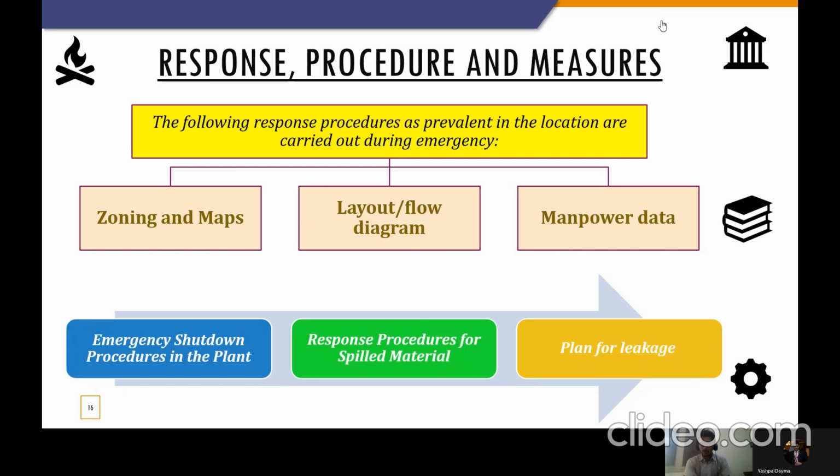So each and every employee or worker should have the knowledge of where the emergency push buttons, emergency valves and emergency switches are, and they should know when to press them and when not to press them. They should also have knowledge of the different sirens, how to activate the siren, and the actual meaning of the siren. Every emergency procedure should be followed as per OISD 144, because that is mostly practiced in every plant or installation.